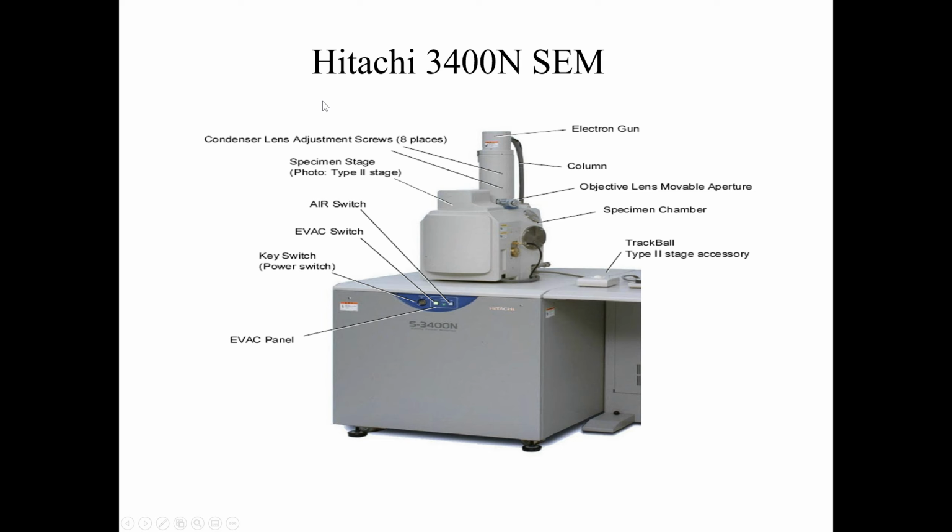The SEM, the scanning electron microscope, there are several vendors of these instruments. Each one has their plus and minuses. The university that I worked at, we settled with Hitachi. They're up and coming. All their electronics are made in-house. Their tech support is second to none. And it's fairly modern, and it's a fairly compact instrument.